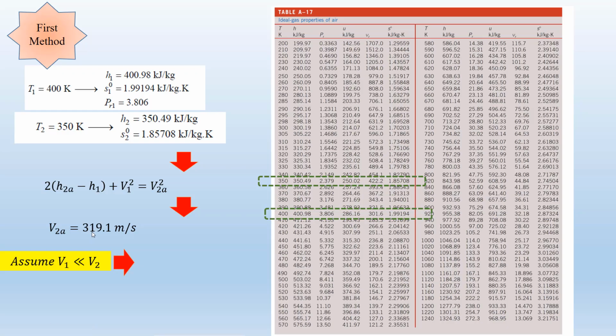So you can use the second equation to calculate the isentropic efficiency of nozzles, correct? To use this equation, you need H1, which you already found, and H2 for the actual nozzle, which you also already found, correct?